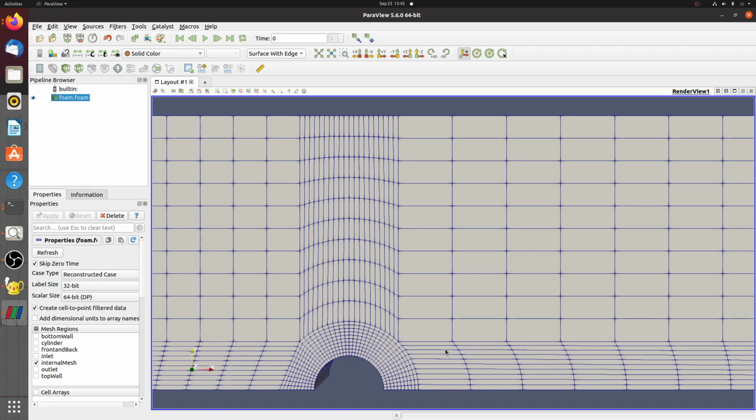So these cells right here should not be greater than 20% larger than this cell right here. And once you have that cell, you can do a gradient to your final cell, whatever size you want it to be. I've shared the gradient calculator in the past, and I'll share it again in the info for this video tutorial.